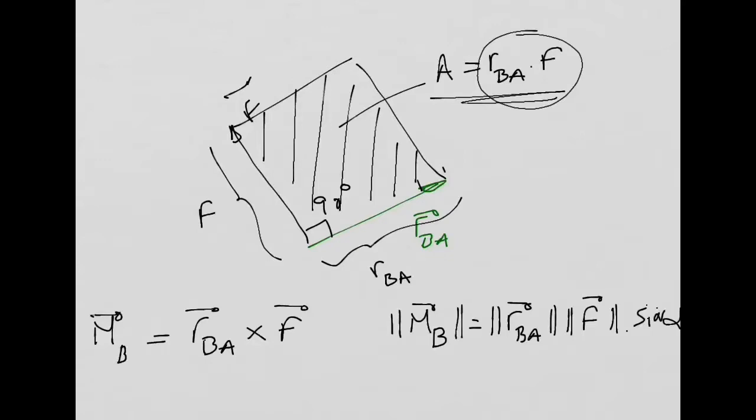No, but I'm saying that's why we're a bit confused, because we would just add up the forces acting... No, a moment is not a force. Right? What you are saying is a force. The resultant of a force acting on a point is still a force. It's not a moment. Right? A moment is when you multiply that force with a distance, then you get a moment. I understand. I'm just saying the confusion comes because at A level, when we used to take moments, we used to understand that as being the resultant force. Please, be quiet. No, if you learned that in A levels, it is not correct. Right? No, that is not a moment.